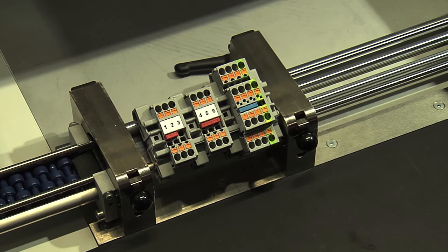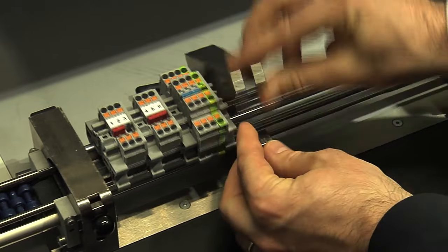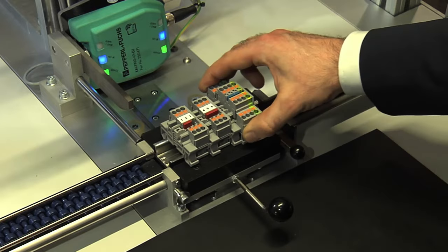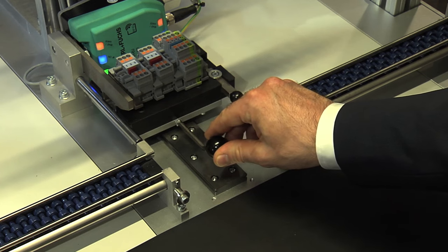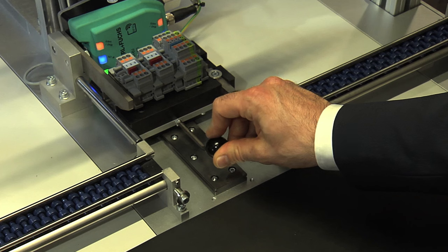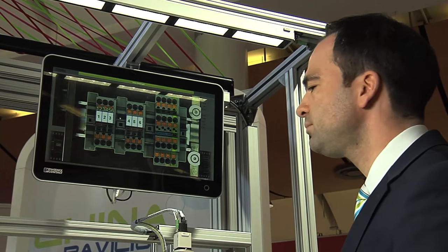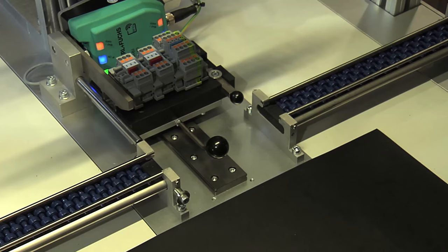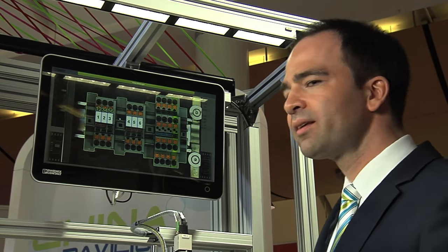The labels and jumpers have now been attached to the block in accordance with the definitions of the virtual prototype, and the block is now fed to the next step, visual inspection. The final step is quality control in the shape of a visual inspection. Once the RFID tag has been read, a vision system captures an image, and this image is compared with the virtual prototype. It is then immediately clear whether or not all components are in the correct positions, and if all the jumpers and labels have been correctly attached. Here we can see that all production and assembly tasks have been successfully completed.